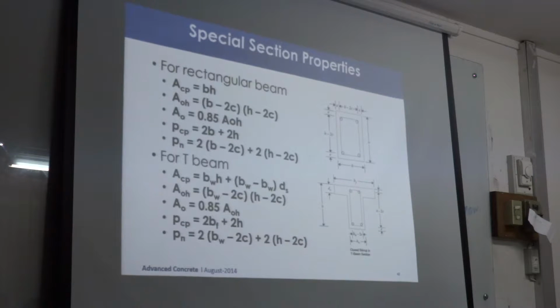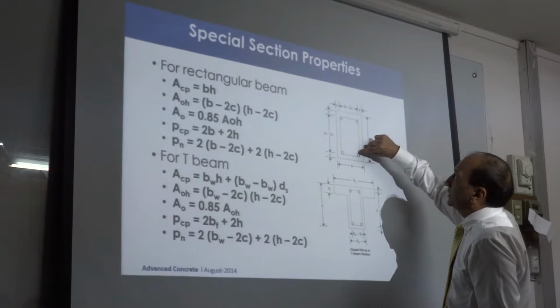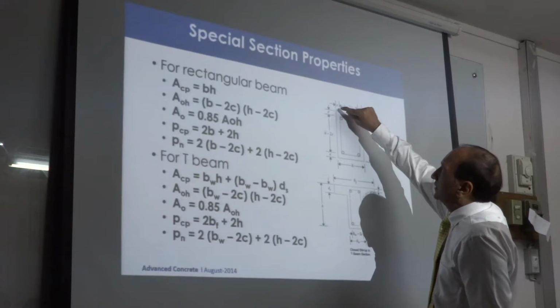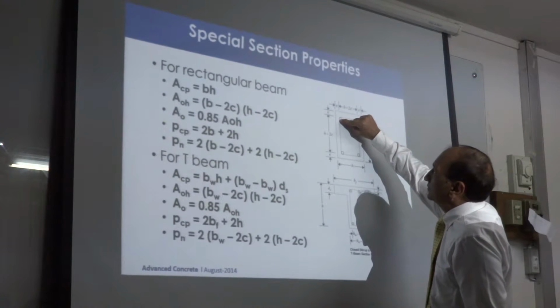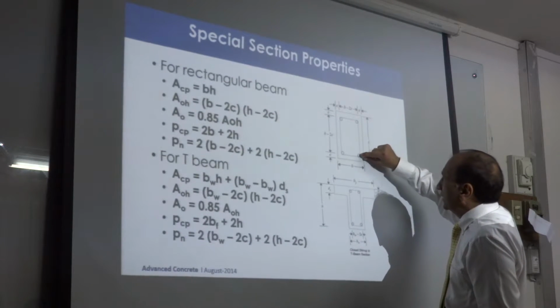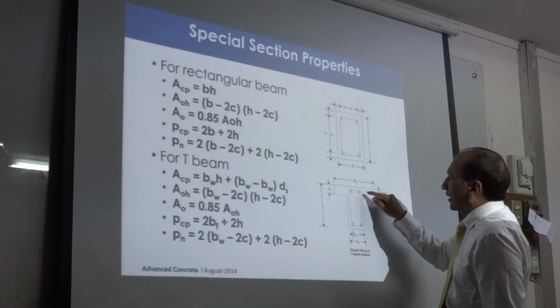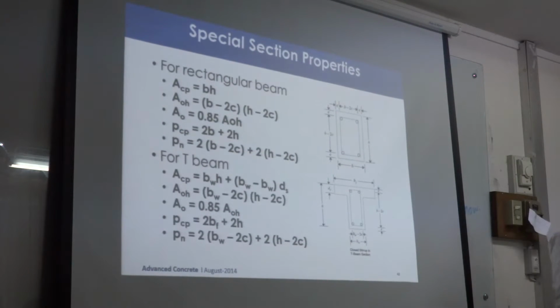Because it's inside the section, no stress there. All the stress in torsion is at the edges of the section. How wide? They define that region to be a certain, let's say, stirrup. So this is the stirrup. So all the concrete, or all the portion in this area plus the stirrups, these are the only ones that we are going to talk about for torsion. The rest is not our concern.